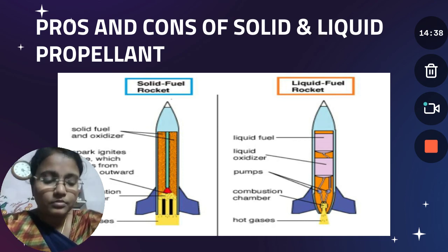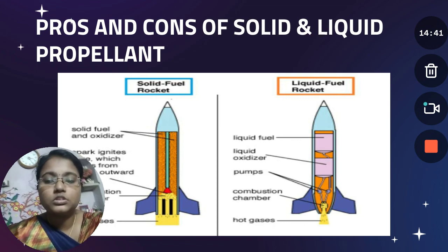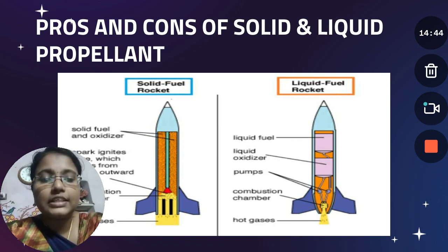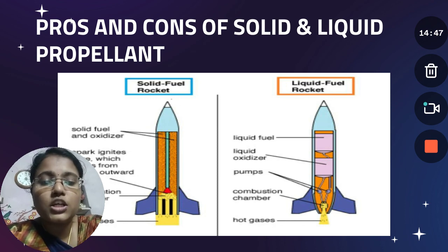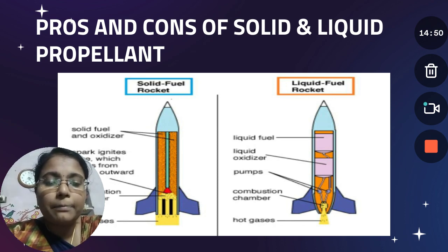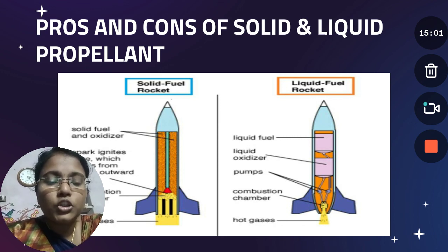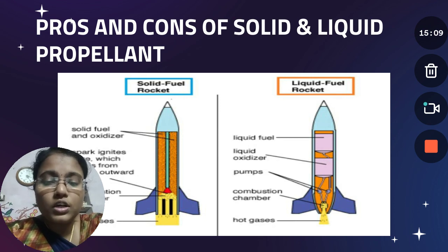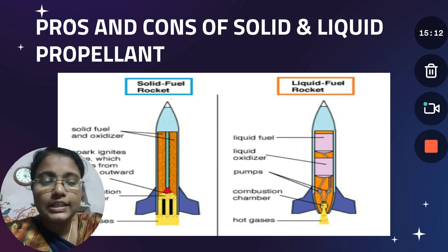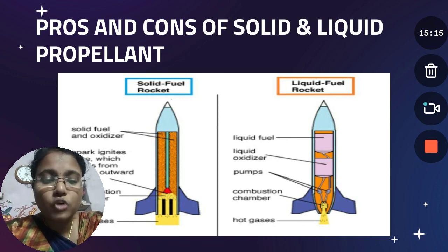Reloading solid fuels requires specialized facilities, whereas liquid fuel potentially only requires a tank, a pump, and a hose. Only rocket manufacturers who want to save money use the cheaper but less useful solid fuel, usually in a fall-away booster or a low-altitude first stage. Liquid fuel provides more control, flexibility, and reusability, and more potential than just for launching, but as propulsion to other planets and the ability to be refueled in space.